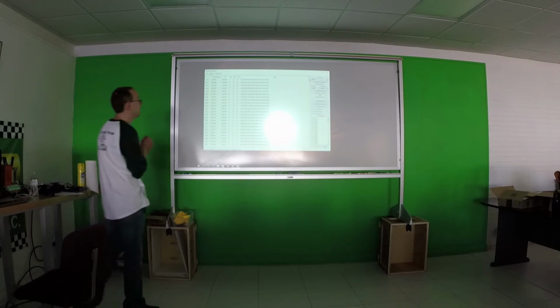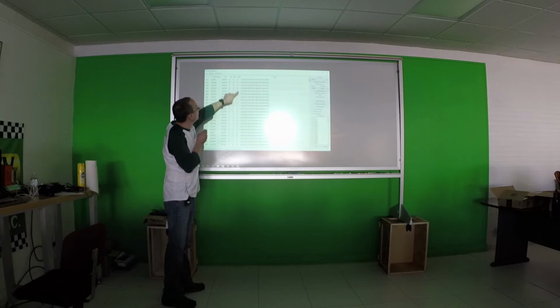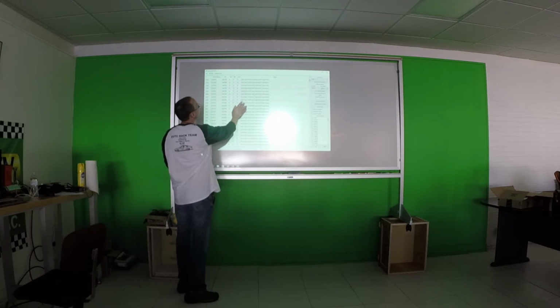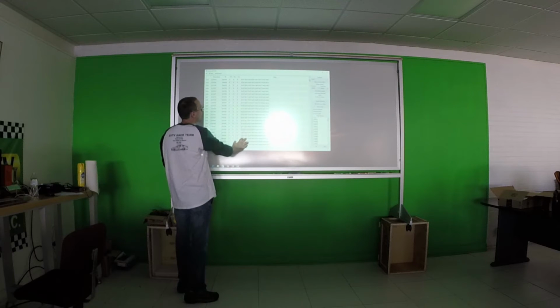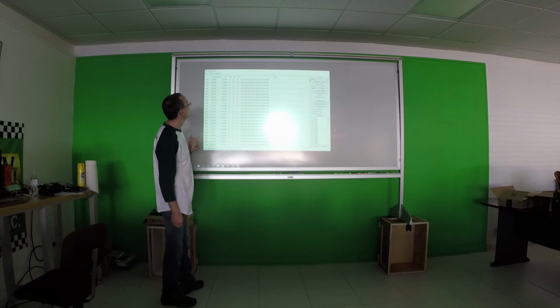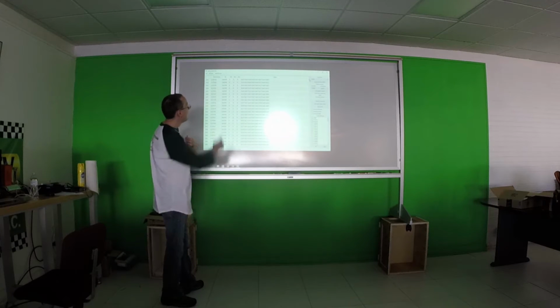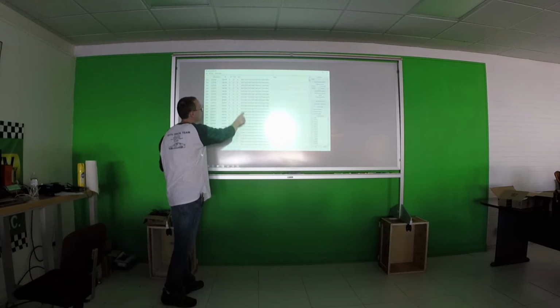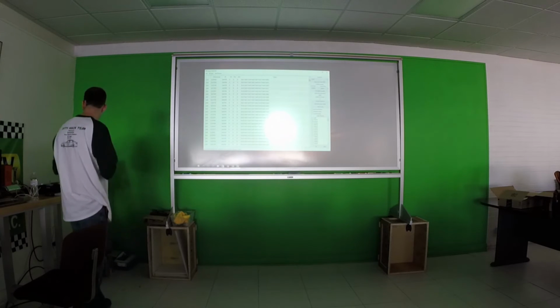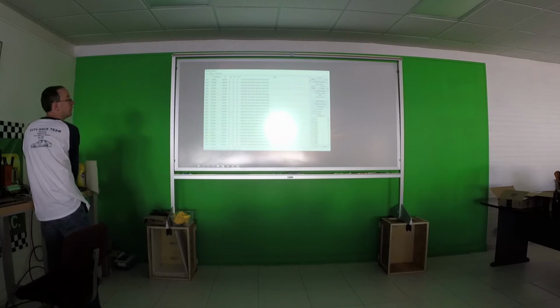Now I can look here. Maybe I'm interested in how these bytes are moving. And if you look here, you can see this is 31, 32, 33. It seems kind of like those values are incrementing slowly, now decrementing here. It seems kind of even. And then you can see that the top thing up there is going 0, 2, 4, 6, 8, A, C, E, and it's cycling. So you can tell this looks like a counter. So sometimes it's nice to filter to only one message and see what's actually changing. As that message continues to be sent on the bus, you want to know what's changing, how the data changes over time. So you can filter that way.